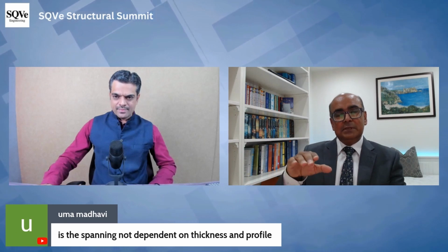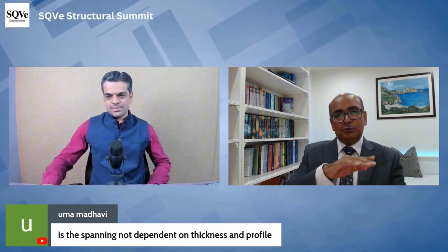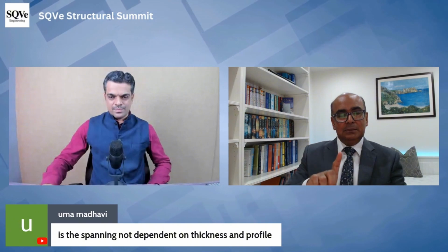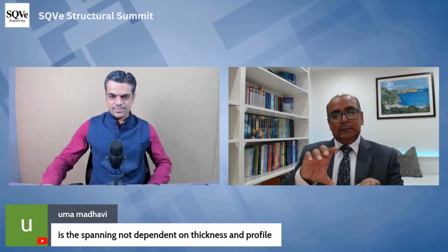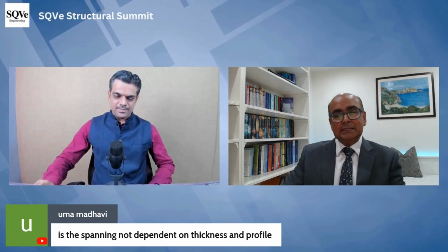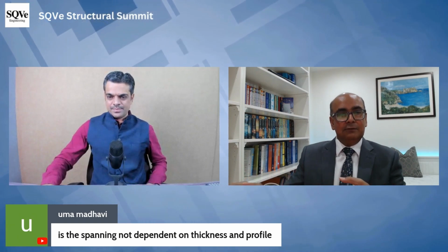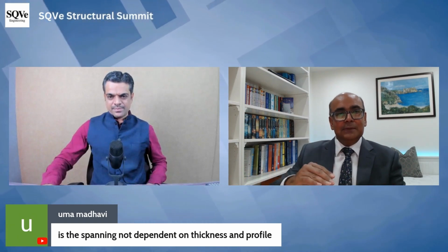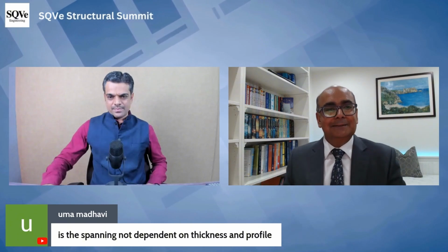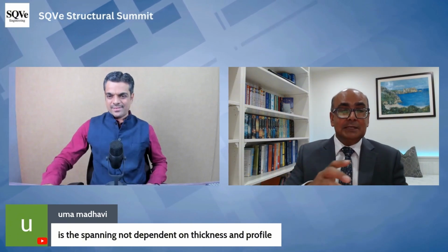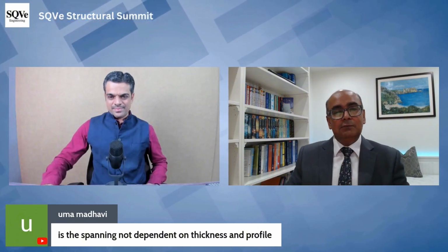So for example, for a 60 millimeter deck, I would use the minimum one, which is 130 millimeter overall depth. And if you increase depth, obviously in load span tables you will have a lot of depth as well, but that increases a lot of dead load on the structure. Unless you have any concern about vibrations and so on, don't use very deep decking. Use deep decking, but don't use a depth of concrete which is quite a lot.